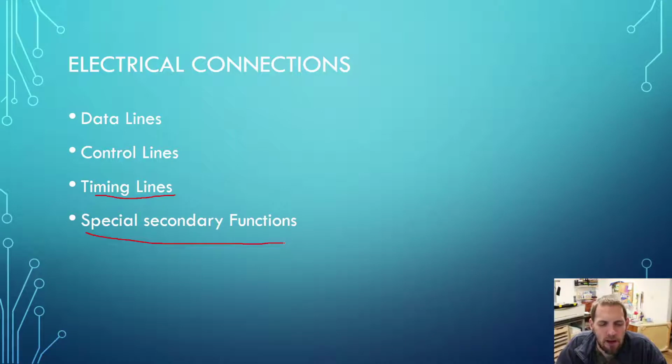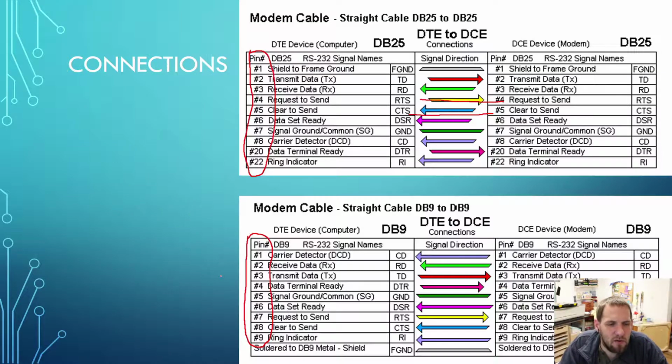So if you have a Siemens PLC to a Siemens HMI or VFD or whatever, there's more control that they can have. Now, sometimes manufacturers omit control lines from their RS232 equipment or assign unusual applications to them. The manufacturer may say, we're not going to follow the standard, right? It's RS, which is recommended standard. We need more special control functions so we can have better, faster communication back and forth and control things a bit more precisely. So they're going to assign more specialty functions to those 25 different lines.